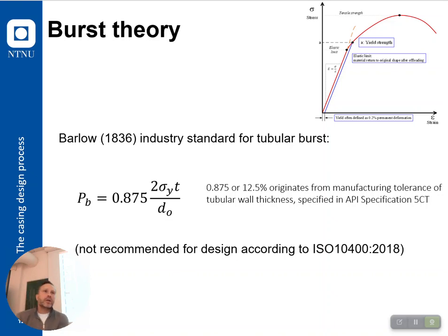Okay, so the pipe will not deform if, let's say this is the wall thickness of the pipe and this is the inside of the wall, trying to make a curve here for the outer wall. You have to increase the stress level so that the level of yield goes all the way through your wall and hits the outside. At that point you will reach permanent deformation and yield, 0.2% yield. So that's another safety factor that is built into the industry burst calculations.